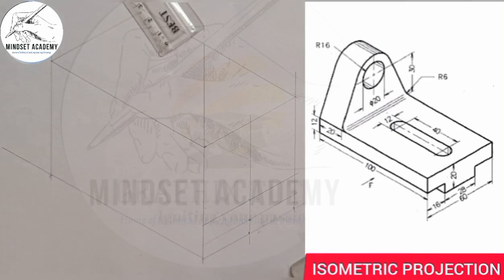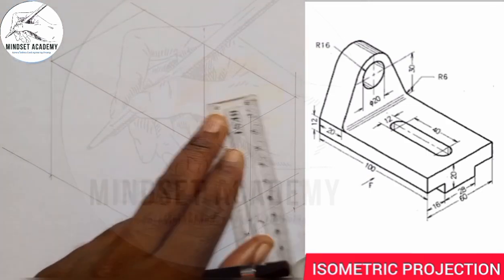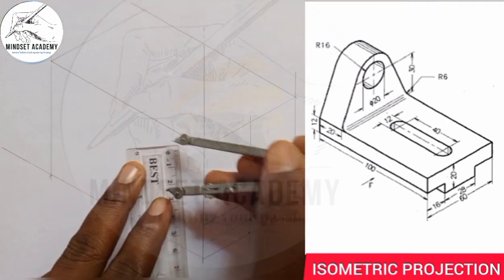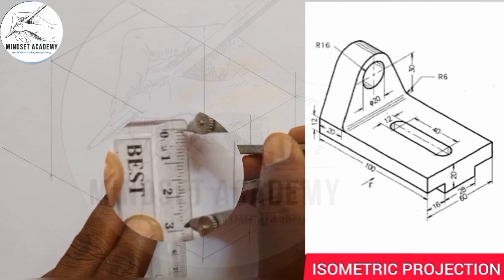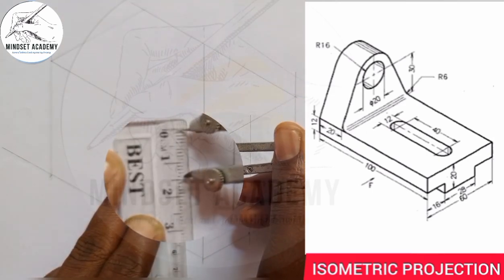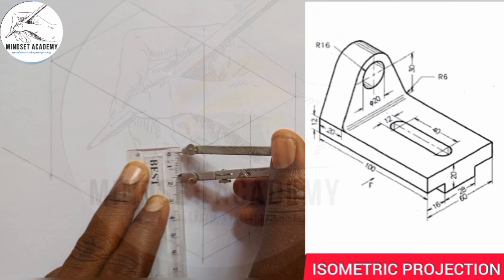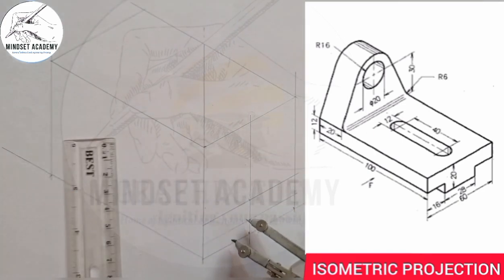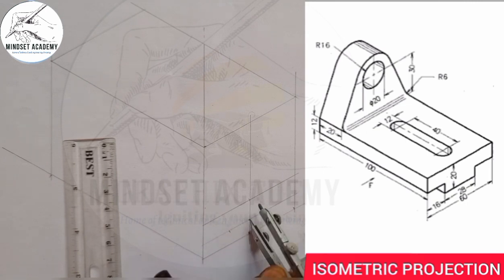You can see that? So we are given the thickness of this point here from here to here to be 28. Then I'm going to take 14, 14 each, right? So I can just take my meter rule and I'll measure 14 here, 0 to 14. I'm using 14 because half of 28 is 14, right? And I'll place it at this point. And I'm going to mark 14 to the left and also I'll mark 14 to the right. You can see that? So that is what I'm going to bring down.